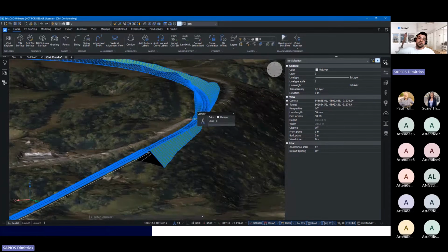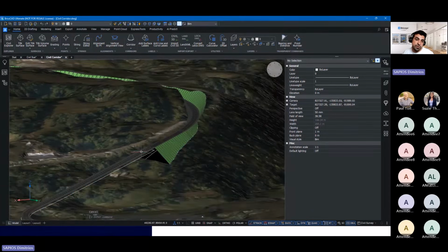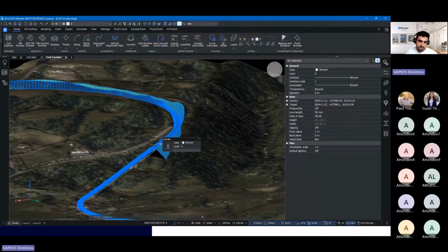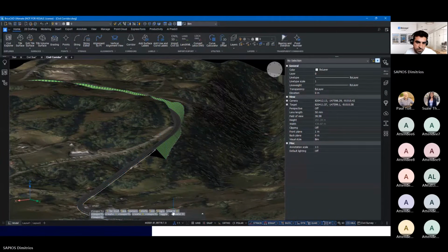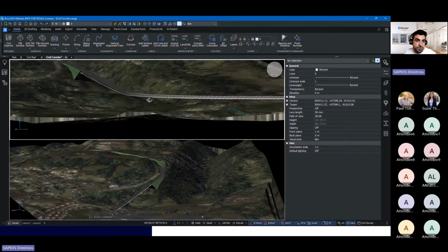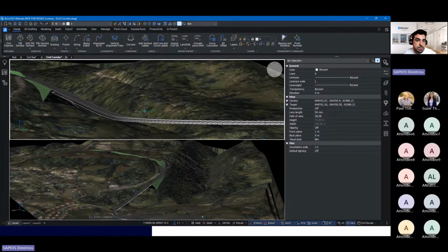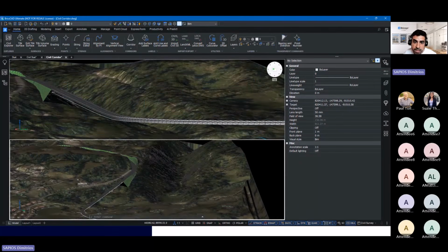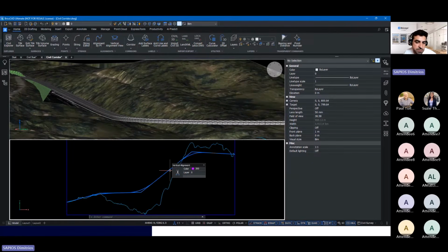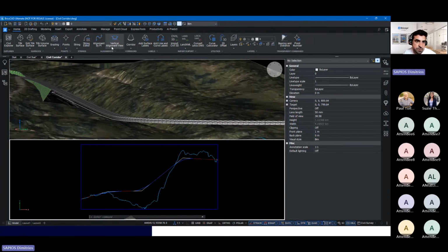And another interesting feature about the corridors is the fact that we can easily edit the vertical alignment in order to control the height of each individual point. Let's see how we do that. In this case, I will enable a secondary viewport to split my screen into two segments because I need to focus on two different areas at the same time. So let's see the corridor from this angle, and on the other angle, I have created a vertical alignment. This is the command, vertical alignment.